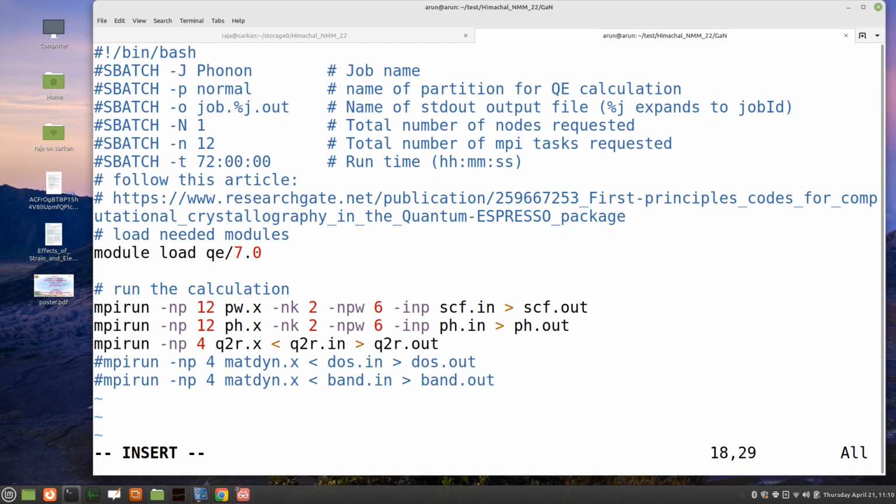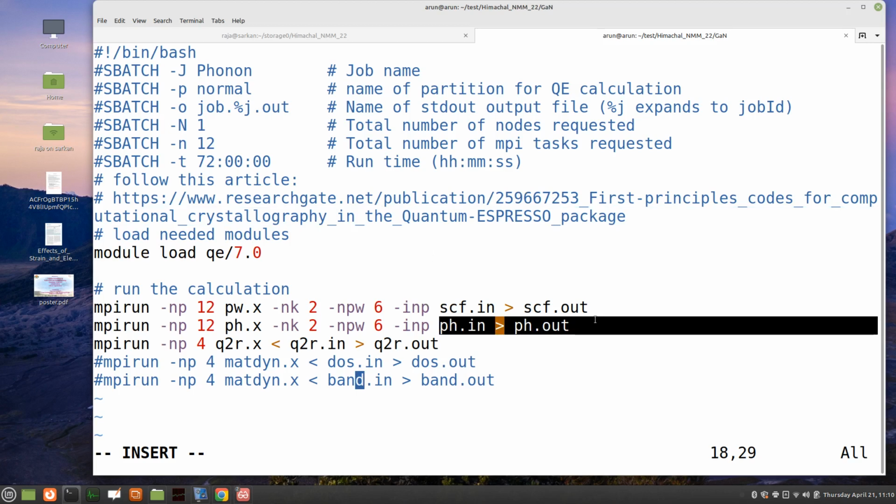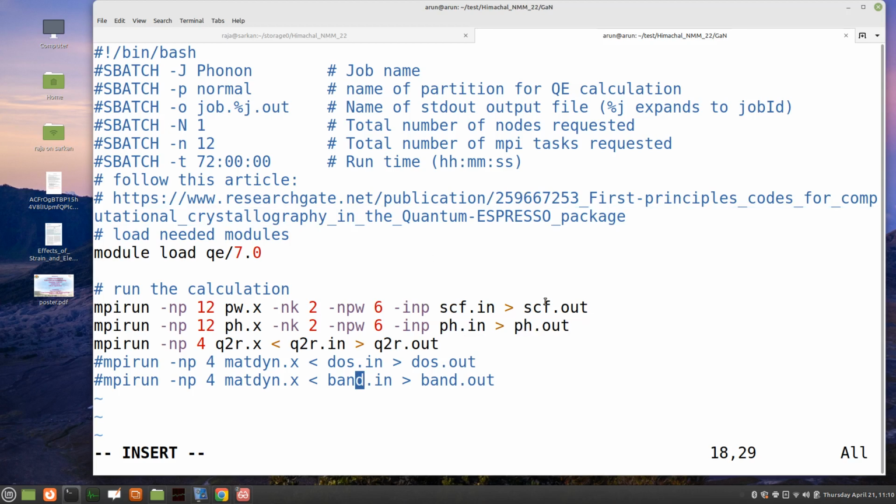You can bring that file locally on your machine, and everything can be run locally, okay? Only thing you cannot run is the PS.in. That is extremely long time. SCF also you can run. It is just 4 atoms. It doesn't take more than half an hour on a local laptop. But this is not possible on a local machine. At least you have to commit weeks and weeks of time for that 443 grid, okay?